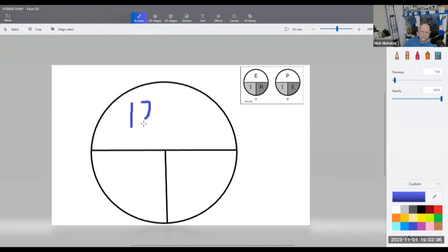So you got 120 goes in the power spot. If they gave you the voltage as 12 volts, put 12 in the voltage spot. Now you got your equation. 120 over 12, you do the math, and your answer is going to be 10. It's that simple.